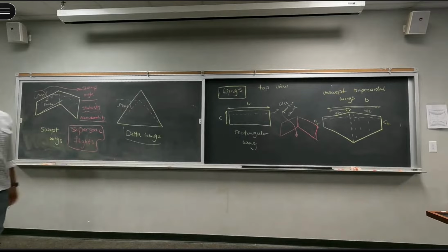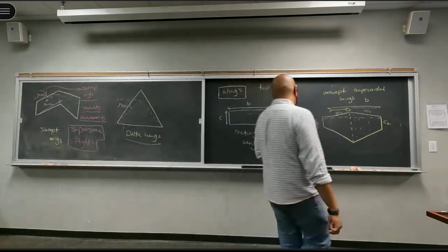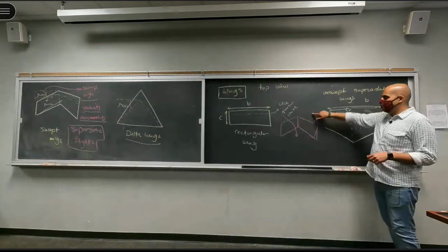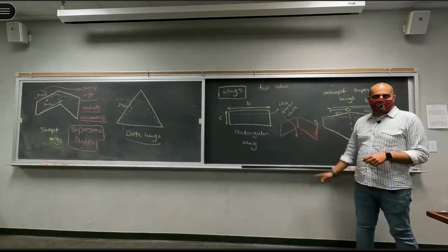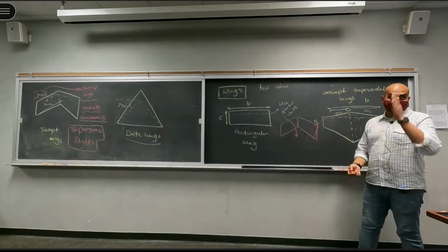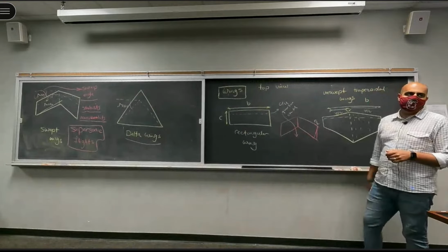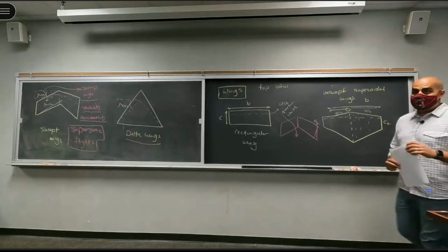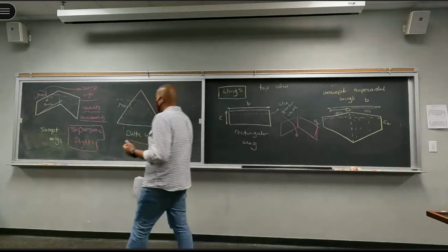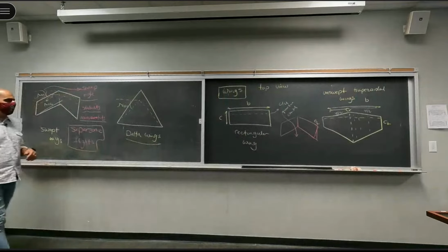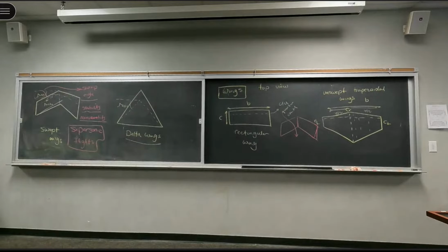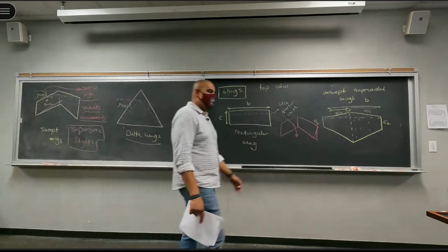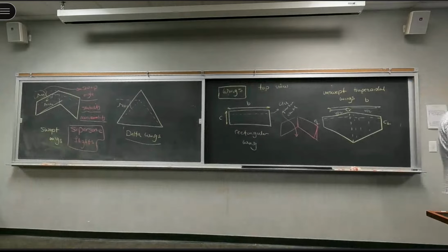Just think about it. As Mohammed and Paul mentioned, your span is going to change, your effective chord length is going to change. The chord length is in front of the flow pattern, and the flow pattern itself is going to change, which means that we will see a lot of changes when it comes to flight mechanics and flight performance in general. So introducing the sweep angle is very important, and you will see later on that swept wings are mostly used in military aircraft because of their specific designs.